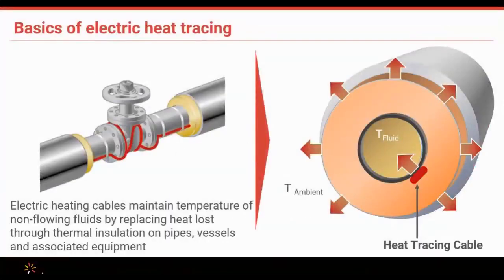So today, we're going to talk really the basics on what heat tracing is and how you guys can look at a project and be a little bit more knowledgeable on what you need to get started. So the basics is you're putting an electric cable on a pipe. In this application, that pipe might be for freeze protection. That pipe also might be for flow maintenance. So depending on what you're looking at, those are the 2 things to consider.